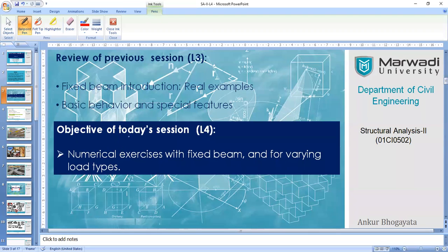So when the horizontal force is completely absent, we can say that the fixed beam is statically indeterminate to 2 degrees, because there are 2 plus 2, 4 reactions, and we have two conditions of equilibrium since we are avoiding sigma H, as there is no force in the horizontal direction. So this is just a point. And if you answer that the degree of indeterminacy of the fixed beam is 3, that is completely fine. It should not be a wrong answer.